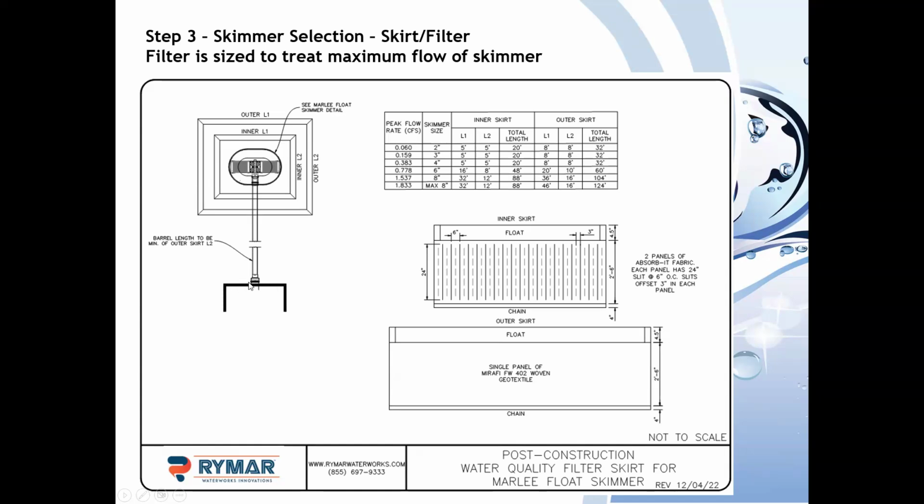Assuming your riser structure is probably not more than 12 or 14 feet, maybe 15 feet tall, a 20-foot piece of pipe will work there. When that riser comes up at a 45, where the skimmer comes up at a 45-degree angle, there's only going to be 10 feet between the skimmer and the riser structure. So we don't want more than 10 feet here, because then the filter is going to start hitting up against the riser.